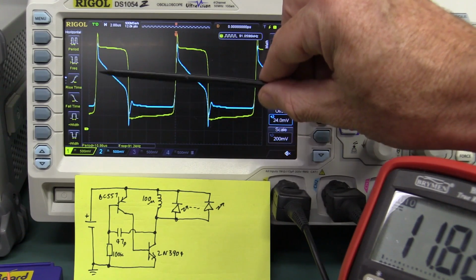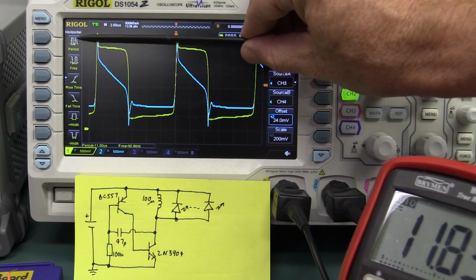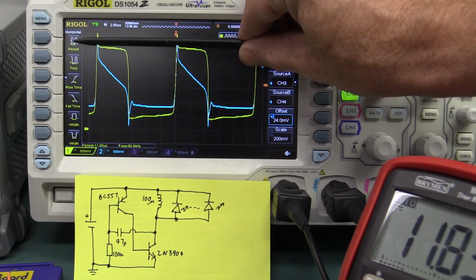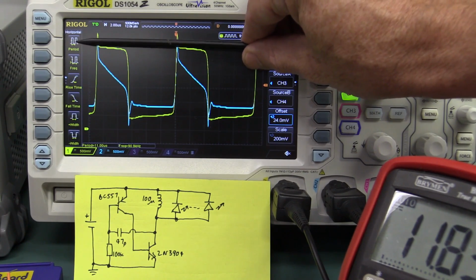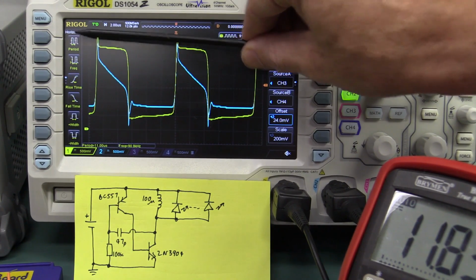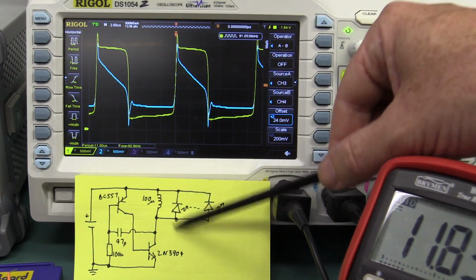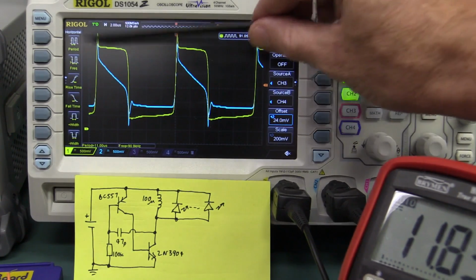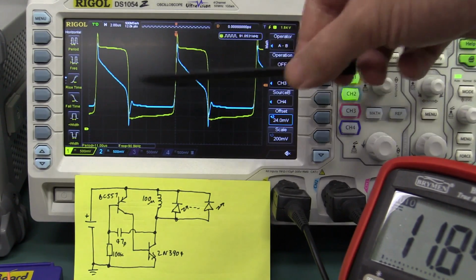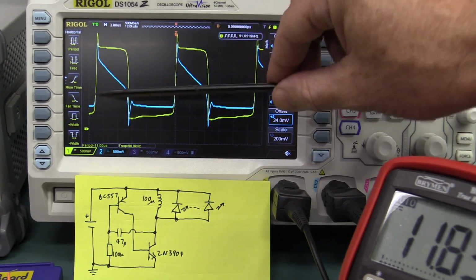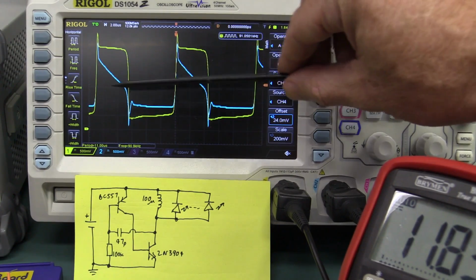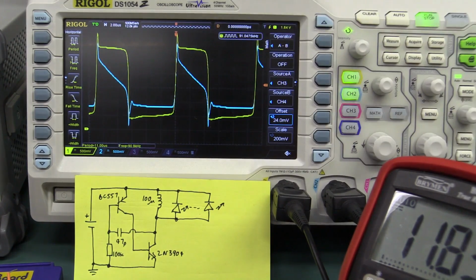500 millivolts, 1 volt, 2 volts, 3 volts. So it's jumping up to around about 3 volts. That's not surprising. We've got our 1.5 volt supply plus our roughly 1.6 volt clamping voltage of our LEDs at the particular current. So yeah, there you go. That's what it's jumped up to. If we remove the LEDs, we would find that the voltage would jump up much higher.